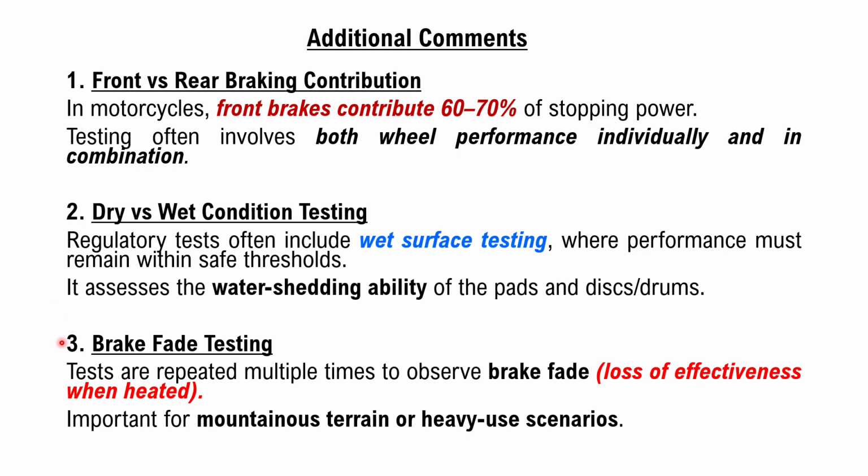Number three, brake fade testing. Tests are repeated multiple times to observe brake fade, that is, loss of effectiveness when heated. It is important for mountainous terrain or heavy duty use.